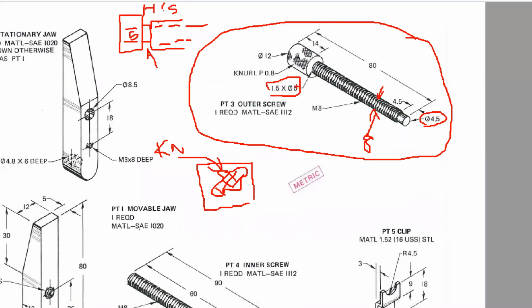So don't try to knurl that. If you cut those knurls in your model, really model the knurl like it's supposed to be, it'll take all your system resources away from you, and your software will move terribly slow. Nobody will be happy with that.